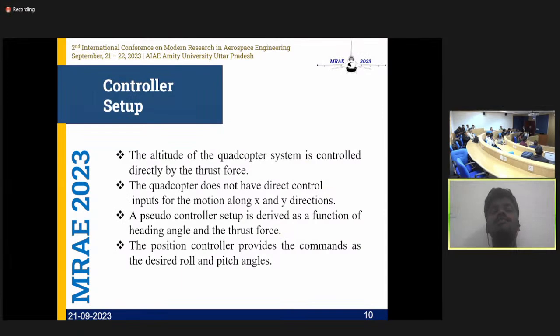The classic pendulum model, which we chose because initially when the work was started, we considered an analogous system to a drone carrying payload. So we considered a cart with a pendulum system, which is a classic example in classical physics, where a moving cart is attached to a pendulum and we model the system. There, the pendulum has only 1 degree of freedom. So what we considered was if the cart has 3 degrees of freedom and the pendulum also has 3 degrees of freedom, and if we are able to build a controller for that setup, that will be an equivalent controller for a drone carrying a slung load setup. So that was our approach, and hence we got the idea of taking only the classic pendulum approach. I hope I clarified your question.